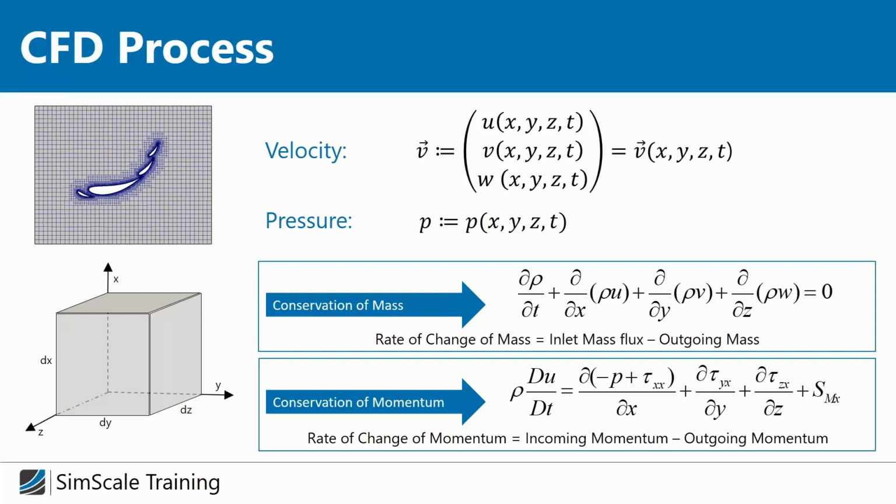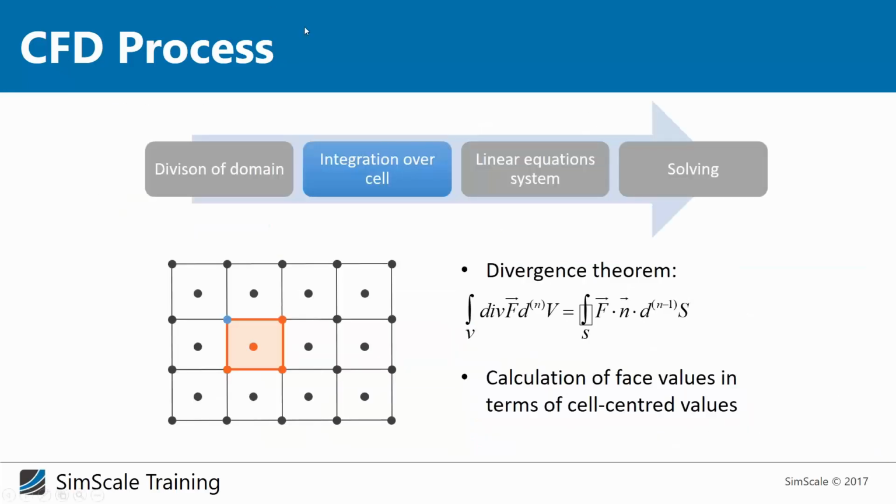We will receive a submodel which represents our problem based on these small finite volumes. It's still not the solution we're looking for, because right now we still have this second-order differential equation we cannot solve. But there's something very nice we can do: applying the so-called divergence theorem, or Gauss theorem, which I'm quite sure you heard about in the past at university. The divergence theorem, at the end of the day, just gives a relation between the flux around a closed surface and the volume this closed surface contains.